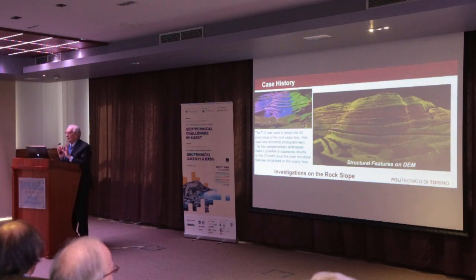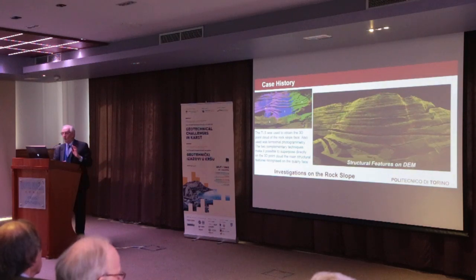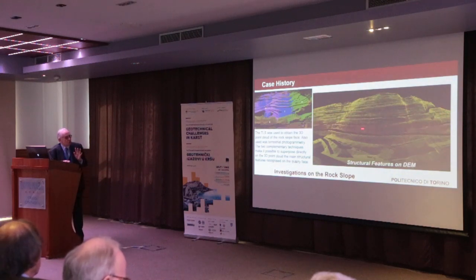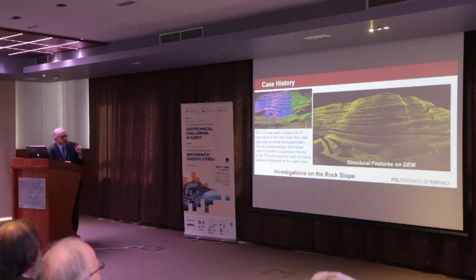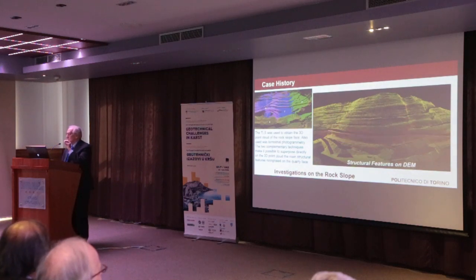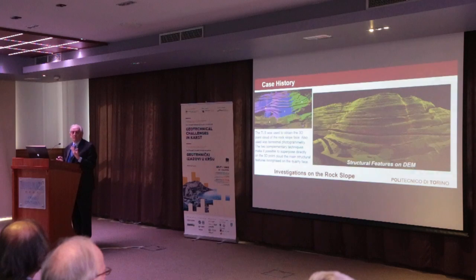not a photograph, but a point cloud, a digital elevation model of the slope, which is allowing me to superpose. I apologize that you are not able to see this picture, but you can see them well in your book. You can see that over here I've been superposing all the structural features. Everything is seen in detail. But what is important, there are millions of points over there. Each point has an XYZ coordinate. It means that I have a three-dimensional picture.